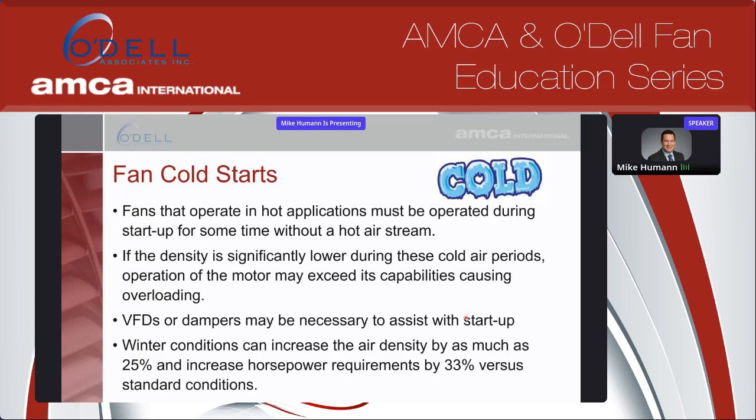And of course, if we're in cold conditions, as most of us are, winter conditions definitely decrease the air density, and that can cause an increase in horsepower. So it's certainly something to consider: what's your worst condition if your fan's outside? If you're at -40, you're certainly going to want to account for that via some motor considerations, or being able to choke back with a damper or on a VFD to overcome that.